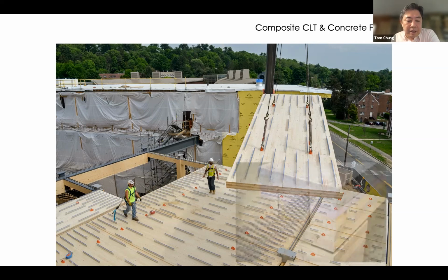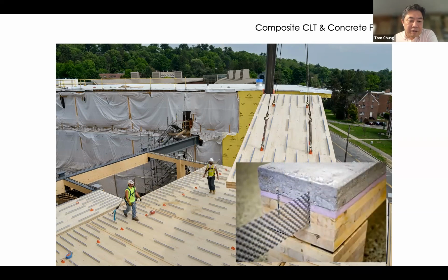At the University of Arkansas, in this case, as typical with mass timber structures on floors, because of the lightness of wood, one of the disadvantages is issues of acoustics and vibration, and you need mass to deal with these very important aspects of public buildings. And so you'll see that typically a concrete topping or a gypcrete topping on top.